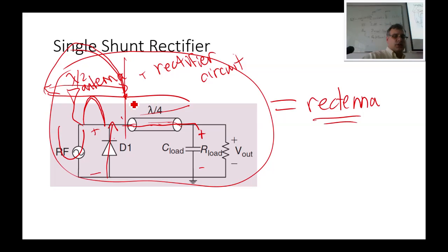But this is the part that enters the transmission line. That leading edge is going to go down. It's going to strike the end of the transmission line. What load does it see at the end of the transmission line? Well, it sees a capacitor. And at high frequency content, or if it hasn't been charged up yet to an initial value, when you hit it with a stimulus, all of a sudden, what does a capacitor look like?